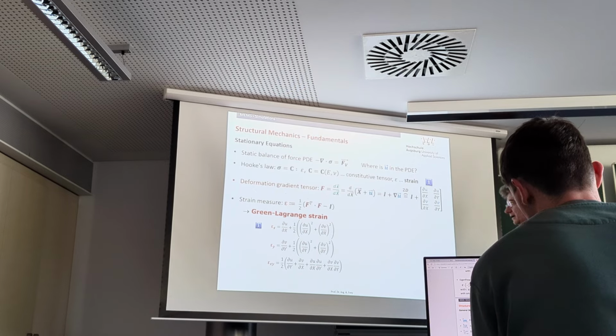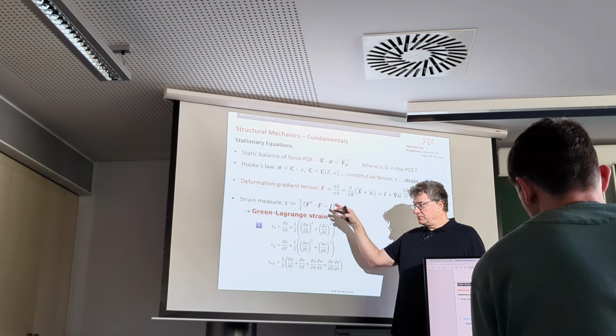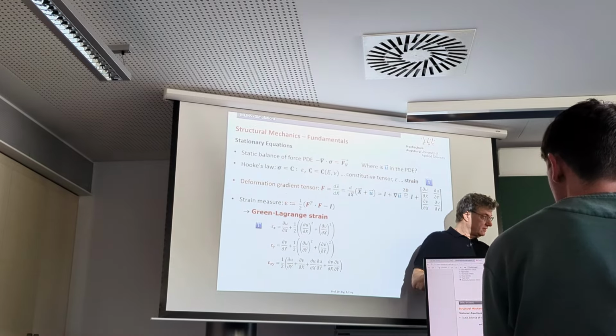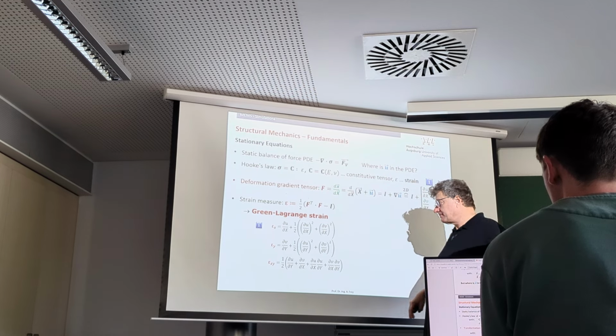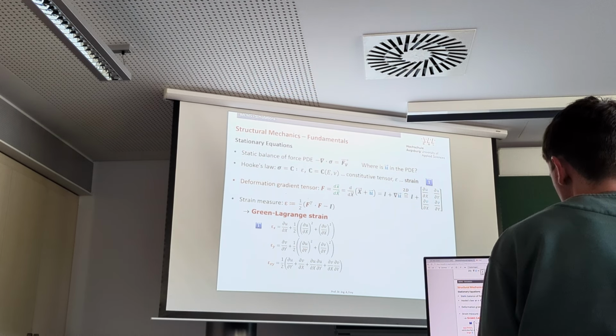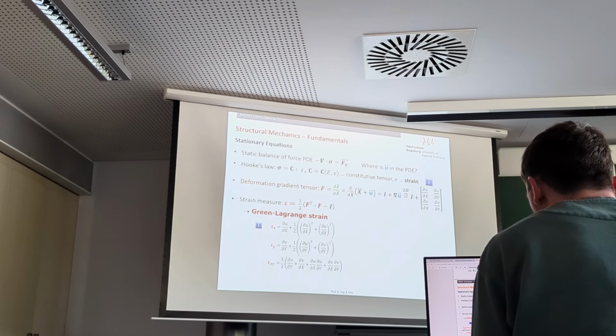Green-Lagrange strain. This is the correct way to calculate strain. If you use this, the program would never calculate stress if you just rotate a square. So why is there anything else? Because these equations are a bit complicated, aren't they?